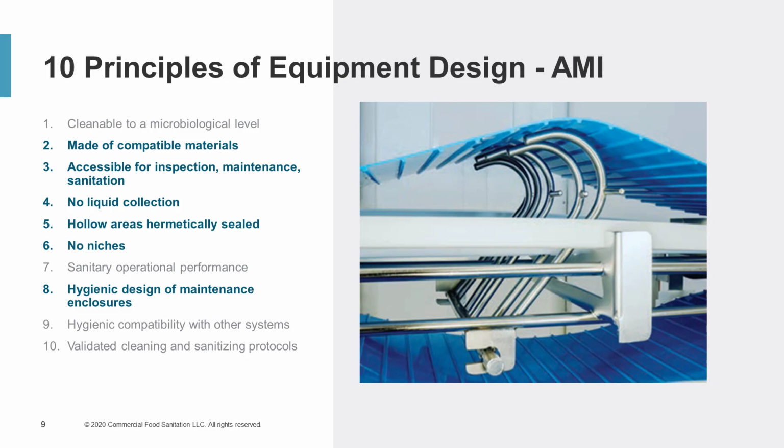Principle number 4, any design should promote the running off of water. The same counts for dust. And then principle number 5, solid materials are preferred. If hollow materials are used, these have to be hermetically sealed to eliminate any ingress of soil, moisture, and with that create a breeding ground for bacteria.